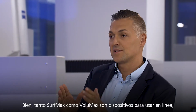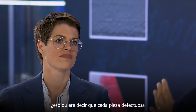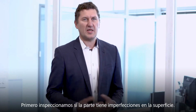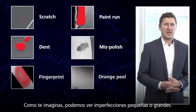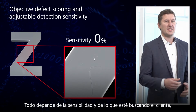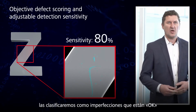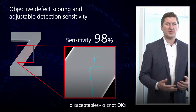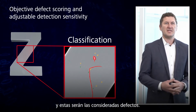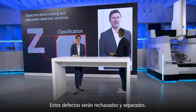Okay, both SurfMax and Volumex are inline devices. Does that mean that each and every defective part gets automatically rejected? At first we're looking, does the part have any imperfections in the surface? As we can imagine, we can see smaller or larger imperfections, and depending on the sensitivity and what the customer really is looking for, we will classify them as okay imperfections or acceptable, or not okay imperfections, and those in this case will be named as a defect. And yes, those defects will be rejected and sorted out.